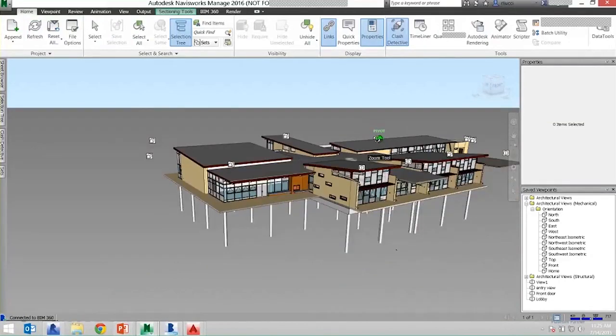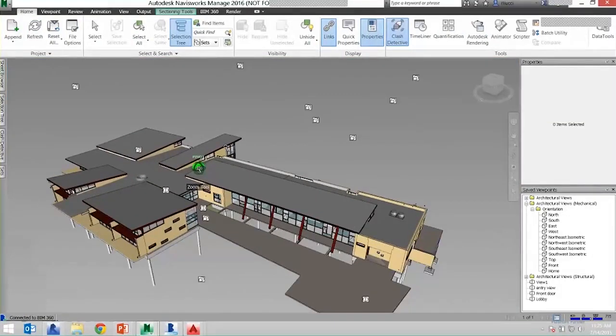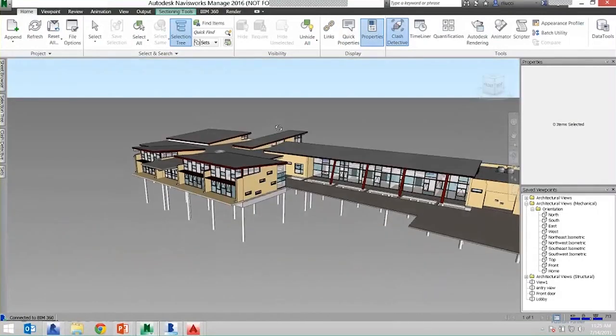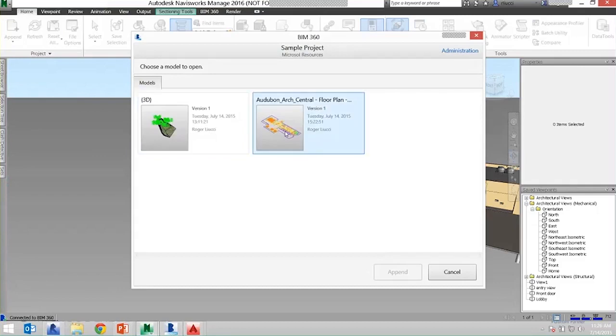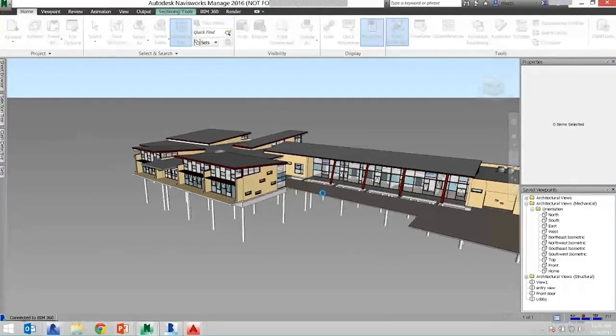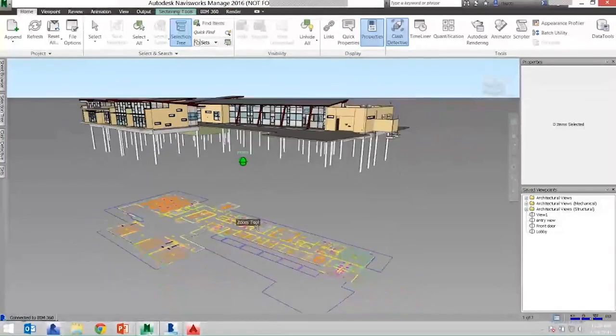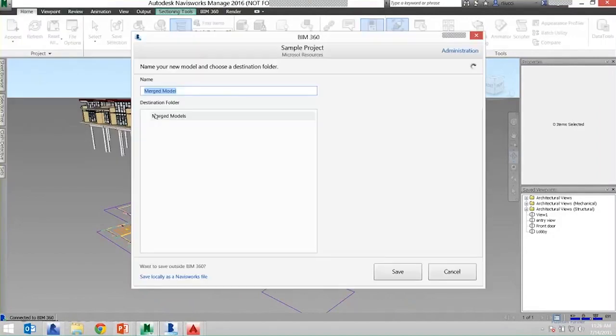So when I'm in Navisworks and I'm adding and merging models together, I don't know if I showed the opportunity of creating additional merge models. For instance, if I'm bringing in files from outside and merging those into my project, we have the ability to take this file and save it out. So I'm making a new merge model with the MEP furniture floor plan. Nice. Love when I do that. Notice I can't leave it that way.